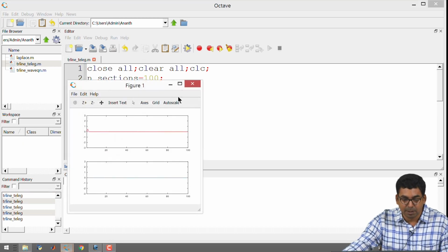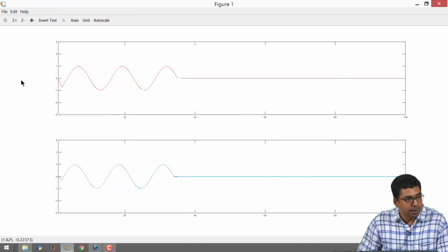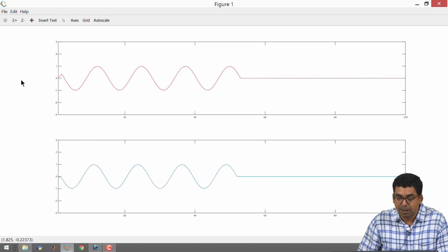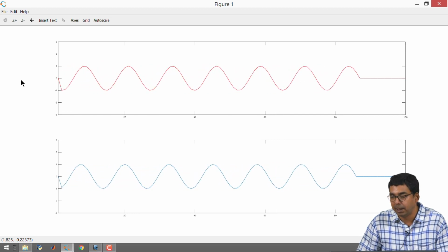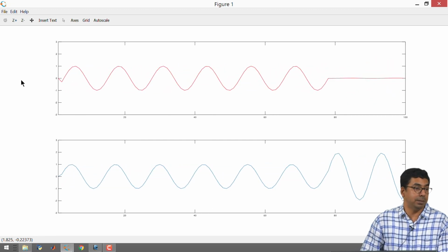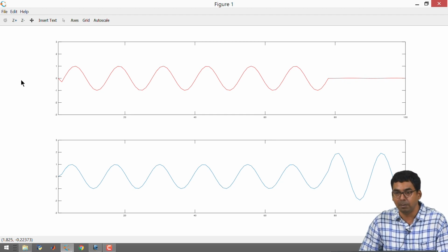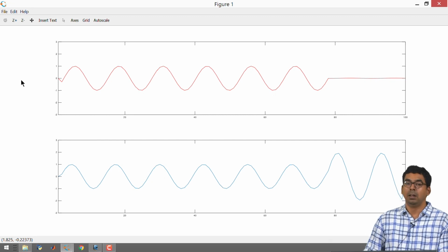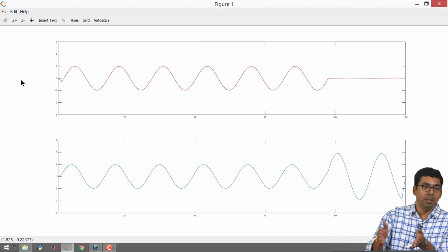Okay. When you excite it with sinusoid, some peculiar things will start to happen and we will have to analyze them. Right. So, here the voltage wave is traveling from one side to the other side. It is going to get reflected completely on the right hand side and it is going to superpose and you are going to get what are known as standing waves. Okay. There will be some specific nodes, specific antinodes for your standing waves and we are going to deal with them. On top of that, we are going to also understand how the impedance of a transmission line will change with length, because some portions are going to have always say 0 voltage or some portions will have 0 current.